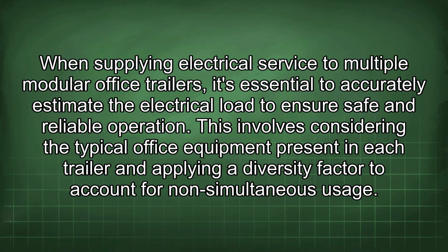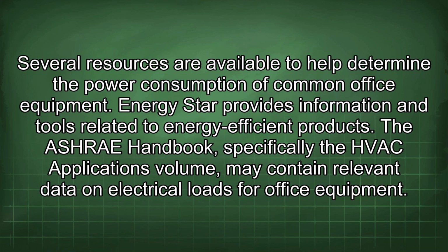When supplying electrical service to multiple modular office trailers, it's essential to accurately estimate the electrical load to ensure safe and reliable operation. This involves considering the typical office equipment present in each trailer and applying a diversity factor to account for non-simultaneous usage. Several resources are available to help determine the power consumption of common office equipment.